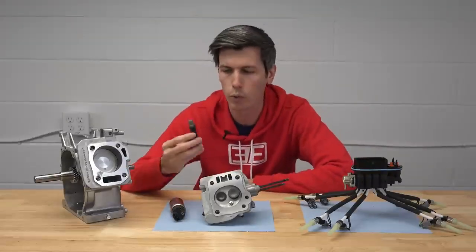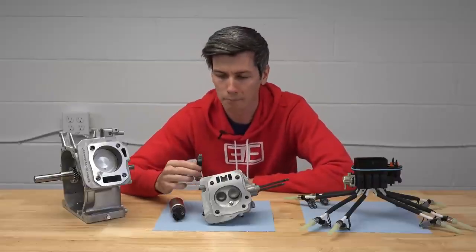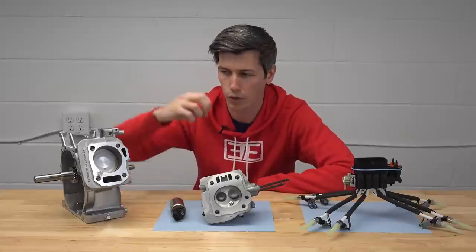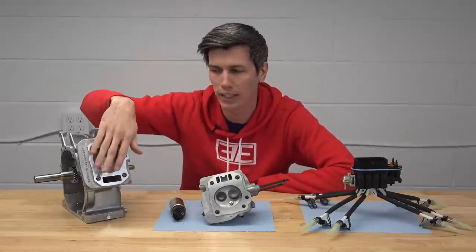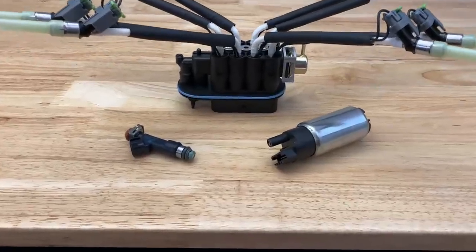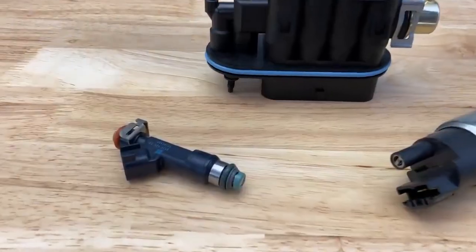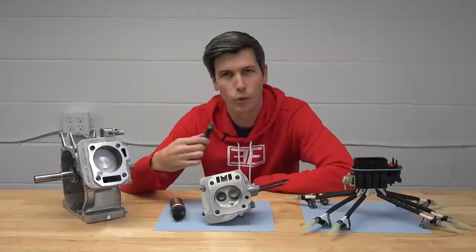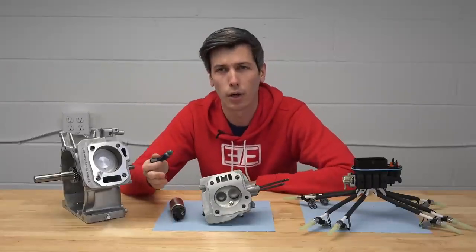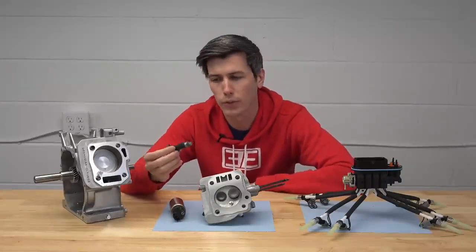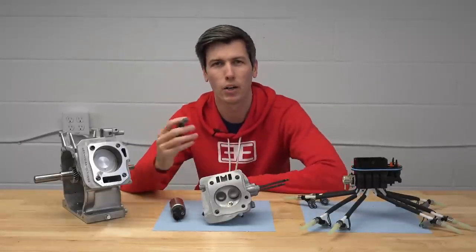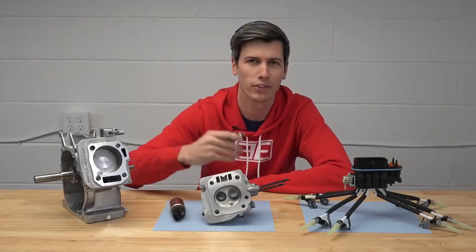But also, there's a cooling effect to injecting that fuel in. When the fuel is injected and it vaporizes, it cools that intake charge. So you can actually pull in more air and fuel into that cylinder and thus make more power. Now, on the other hand, if efficiency is your goal, then you're not going to run that super rich air-fuel mixture. You're going to lean it out a bit. And so, regardless of whether you're at idle or mid-throttle or full throttle, high engine RPM, low engine RPM, electronic fuel injection is going to give you control over how that air-fuel ratio changes depending on how your scenario changes and what you're asking from the engine.